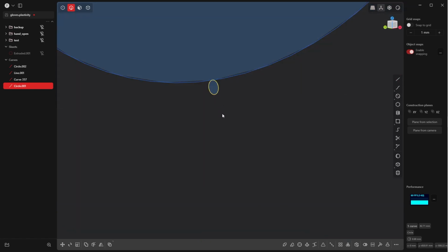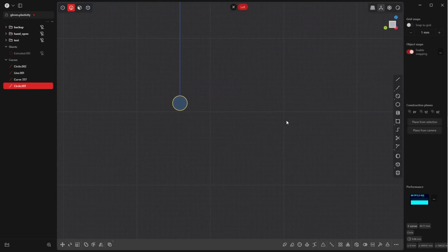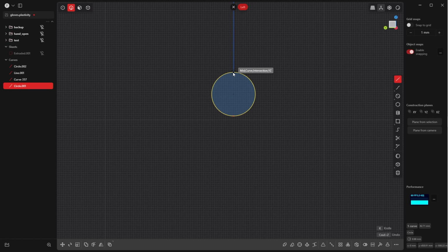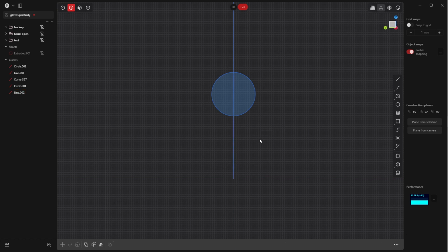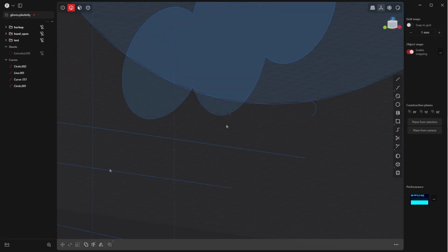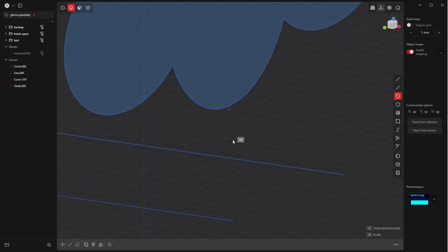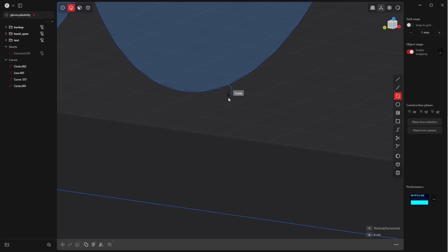And we just need the half of this curve. So first of all, let's go to left view or right view. Again, let's create a line here, starting here at the middle, and again along the Z-axis. Press OK. And if we press T for trim, we should be fine. Okay, that's what we wanted. The next step is creating, again, 3 circles. The first one can be, again, a 2-point circle. And this time, this 2-point circle can start here.